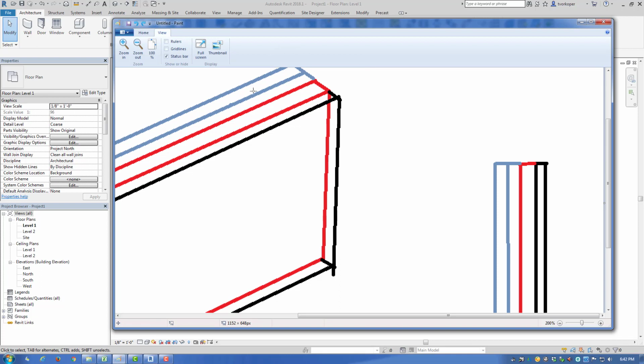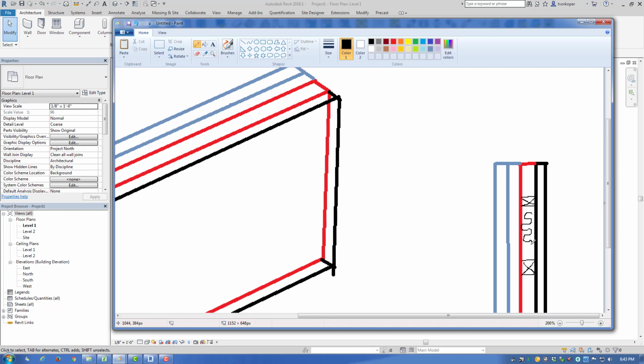What you might notice the difference between how Revit thinks about a wall and in the real world is Revit sees this stud layer as just a plane. But in reality, studs are built every 16 or every 24 inches inside this plane. And it's really not a solid plane at all in real life. It's an airspace filled up with studs, spaced evenly, and then usually some insulation in between. But we don't usually model all these studs or the insulation.